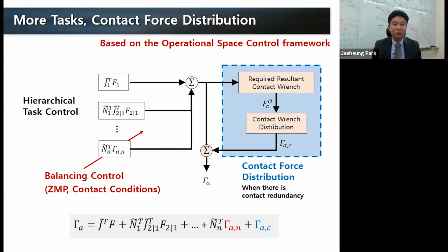Balancing control is really critical, of course, for a floating robot. So we really have to observe the ZMP condition and non-slipping conditions in order not to fall down. In our control framework currently, this balancing condition is met by sacrificing lower priority tasks. So in the end, we can meet these inequality constraints while we execute the higher priority tasks. As a result, the outcome of this control approach is almost equivalent to the result from other control approaches, such as hierarchical quadratic programming approaches, because we are, in essence, meeting these inequality constraints and at the same time controlling tasks with strict task priorities. Hierarchical control.